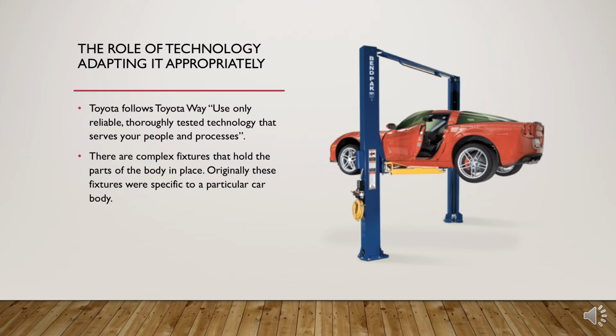But Toyota's body shop still was not very flexible because it used very expensive pallets that were designed to hold the body parts in place for different cars. For example, there would be a Camry pallet and an Avalon pallet, and you could not change the mix of Camrys and Avalons that could run, for example going from 70% Camry to 80% Camry, without building new pallets and changing the mix of pallets, an expensive and time-consuming proposition.